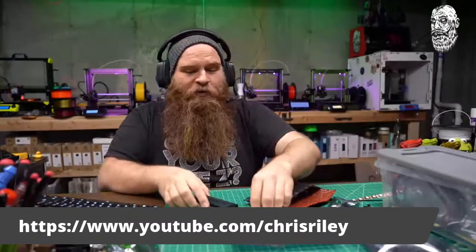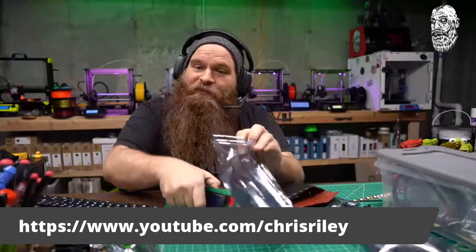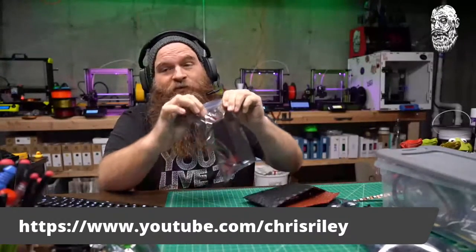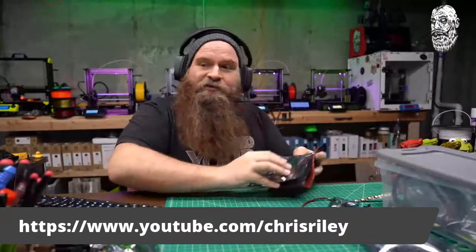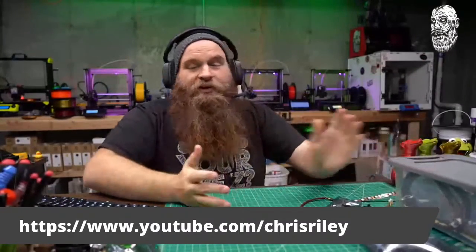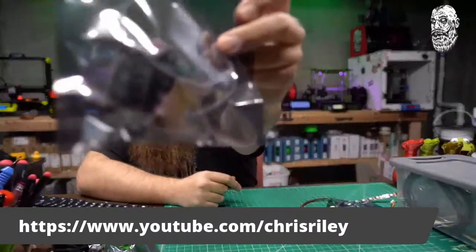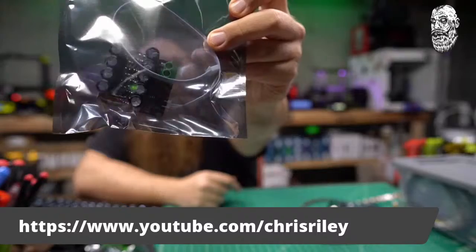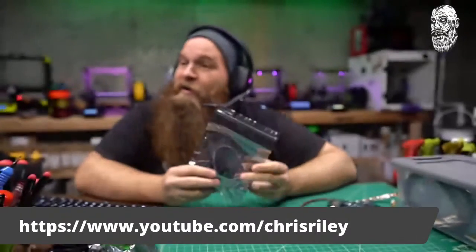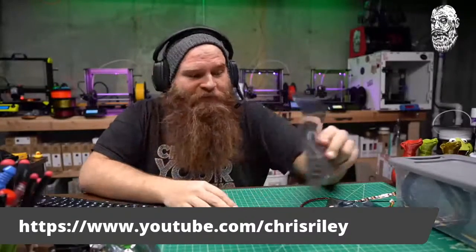This will help you out when you're working on your printer, because if you don't know what you have, it's really hard to set up Marlin. You're just going to start guessing, because we're doing this from scratch. We're not going to use one of the pre-configured things and all that fun stuff. There are other options too. Do you have a battery backup? This is one of those large capacitor setups that act as a battery backup. Are you going to add one? This matters. If you don't have one, we're not going to enable that feature.